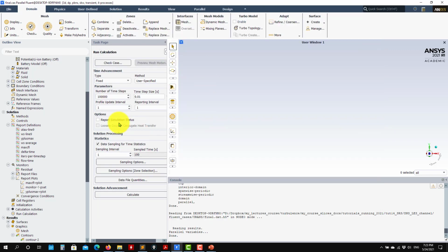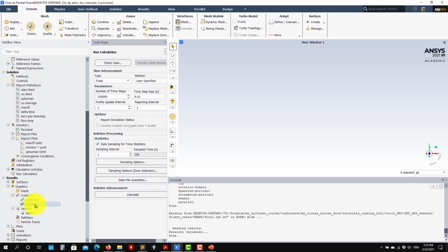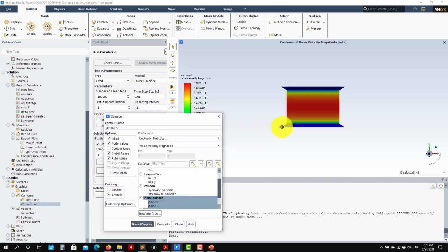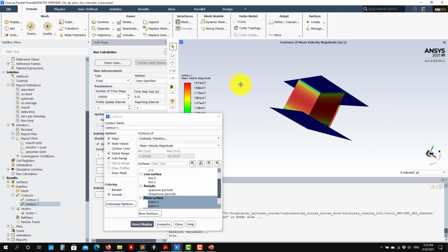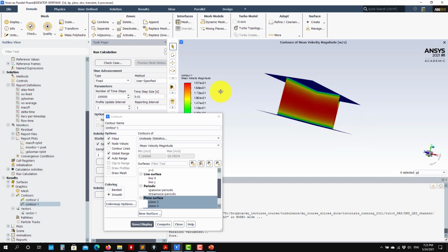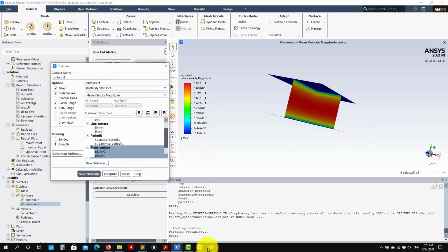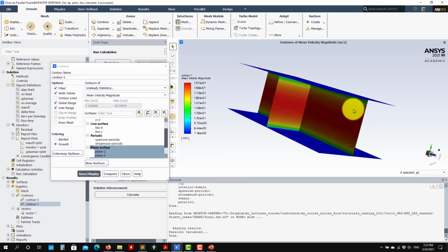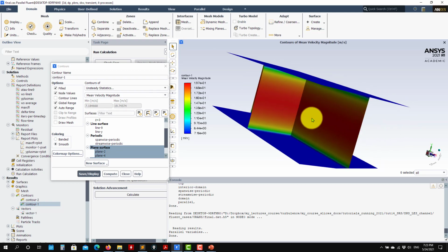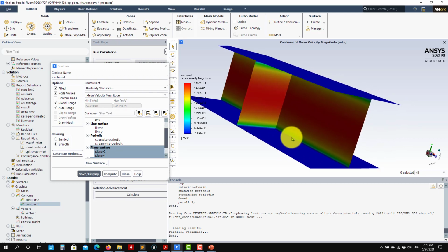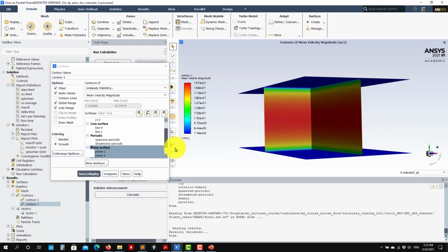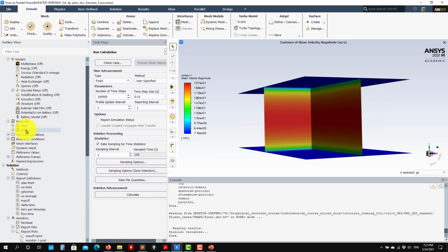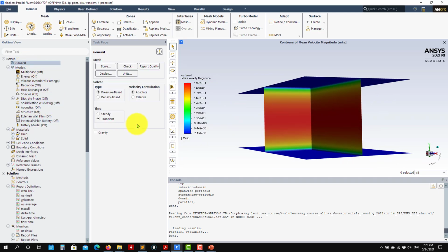And the point here, okay, see that we have a solution here. Basically this is a solution obtained from the runs, but you can also perturbate it. You will see that the URANS will also smooth those fluctuations. Unless you use a very small mesh, you are not going to see those fluctuations. The thing that I want to point out is that now it is unsteady, remember, transient time step.